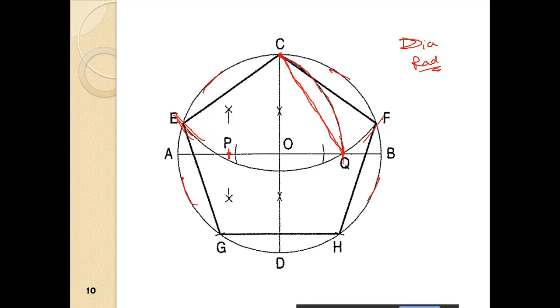All right, so ultimately you have the points E and F. Once you have the points E and F, again the same radius. Now at E you take the center and you draw the arc at G. Now you shift the center to F. From F you take a center and you mark H at this intersection here.